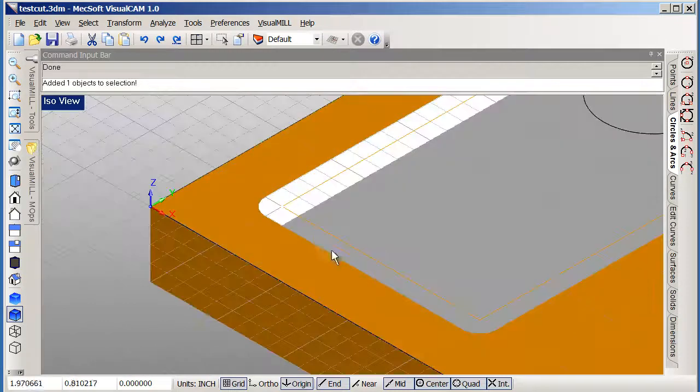especially here in the corner, notice that this line here is my actual drawing. The cutter has gone outside of that, and it's gone outside of that half the dimension of the cutter, which means it has faced this square area here to the depth that we wanted.